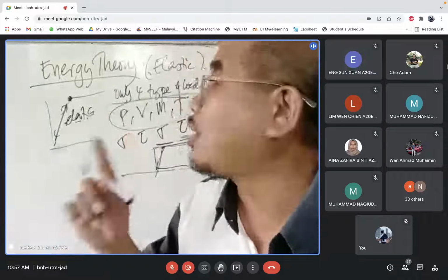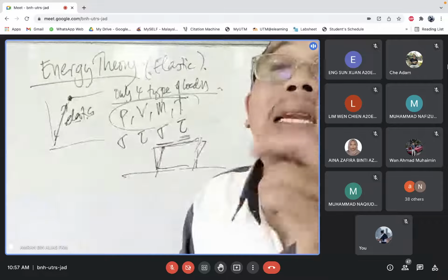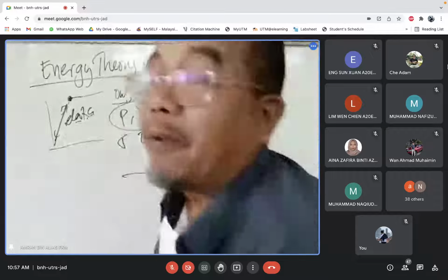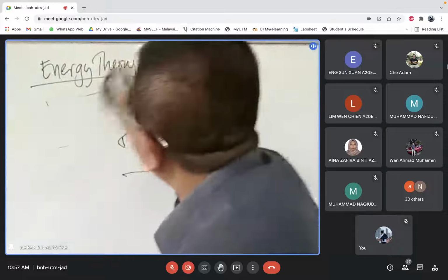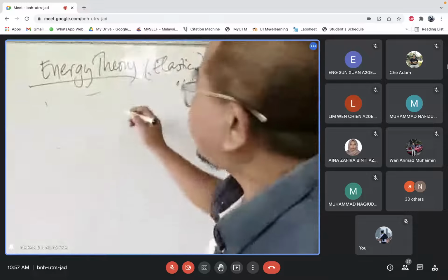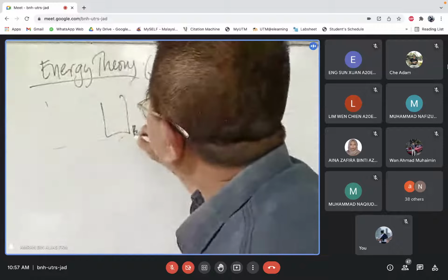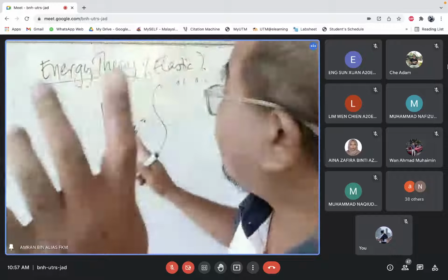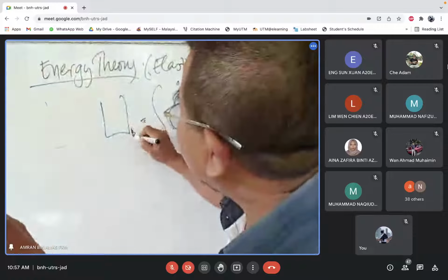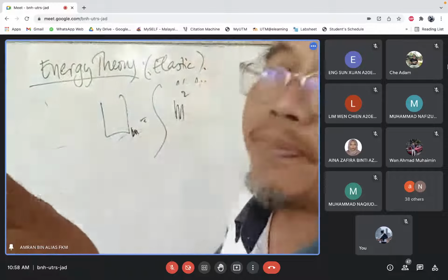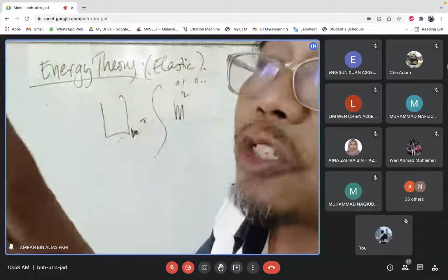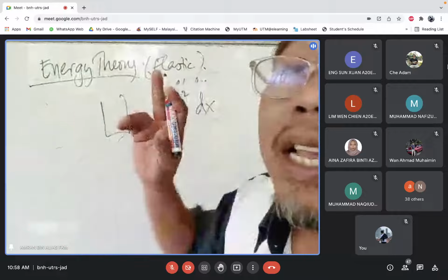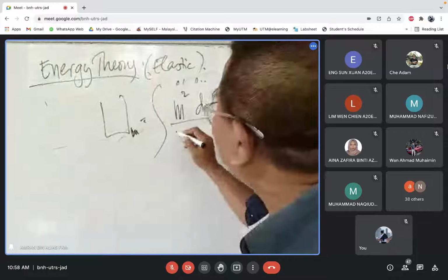Yes. So we are talking about that. How to calculate the energy in those four? Very simple, the formula is very simple. Energy U by bending: the basic energy is by bending moment, so it must be the moment squared, integrated over the distance, and then divided by 2.